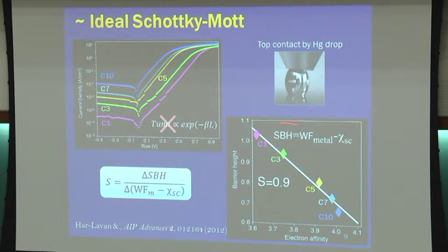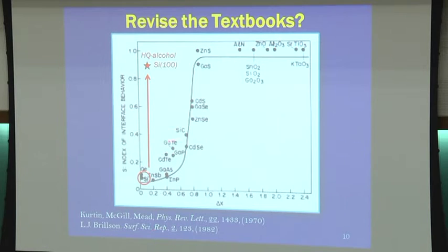It's negative because, again, that's the Schottky-Mott relation, so it's negative with respect to the work function of the silicon, electron affinity. And so the trend is correct. The slope here is 0.9. And that means that this S factor is approaching unity, which is very surprising for us, because this is the textbook, again, from the 70s. This is kind of well-known knowledge in solid-state electronics.